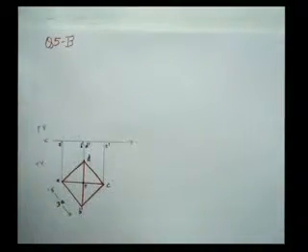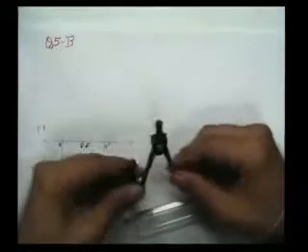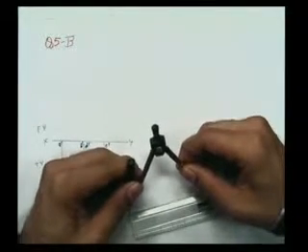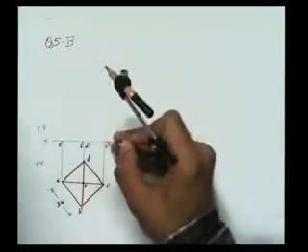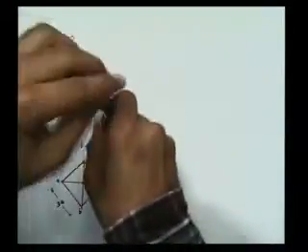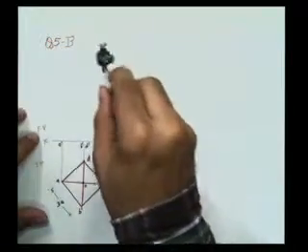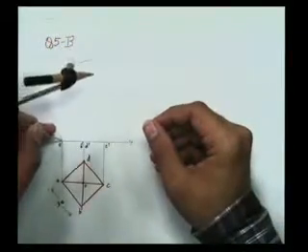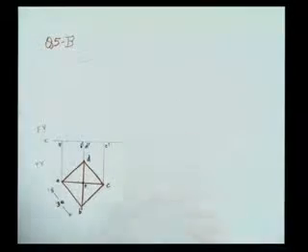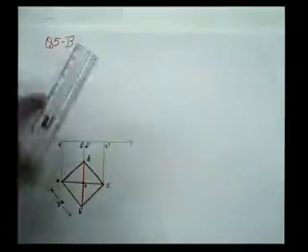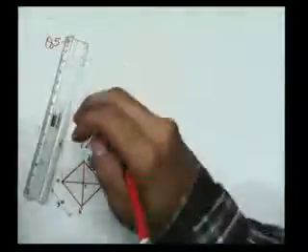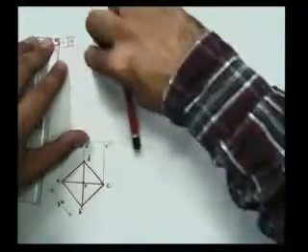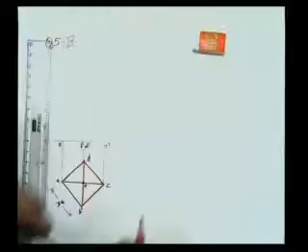And now 80 mm is the slant edge that is given to me, so of the pyramid. So 80 mm I'll take on my compass. Putting my point at C, I'll first cut an arc here. Thereafter again I will cut an arc this way. So then join this. Just draw the arc again.